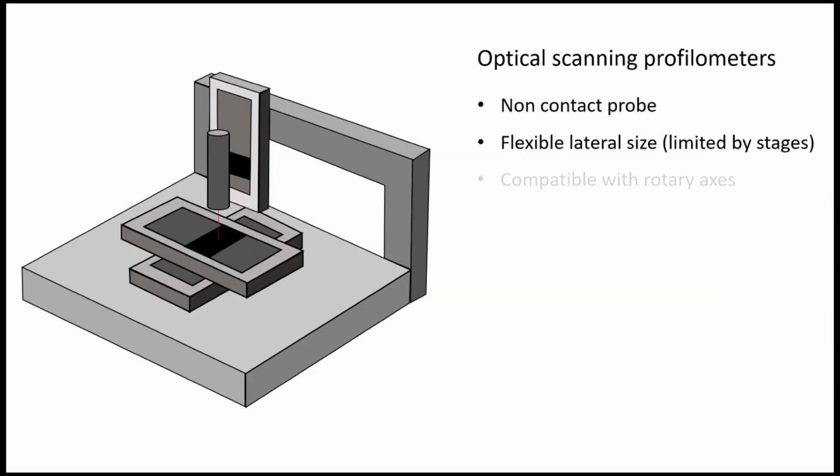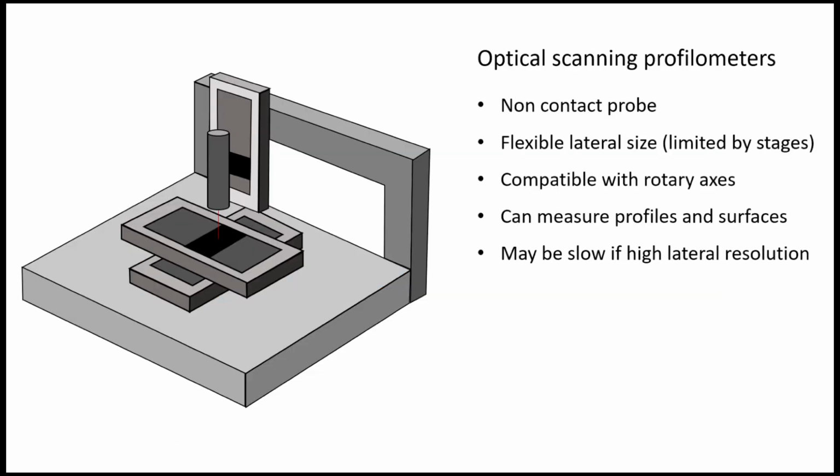Historically, the first 3D profilometers were built from 2D instruments by adding a Y-stage. Parallel profiles were recorded to reconstruct a rectangular area. To overcome these speed limitations, modern scanning profilometers use single-point optical sensors. Because they are non-contact, measurements can be faster than with a stylus-based probe.